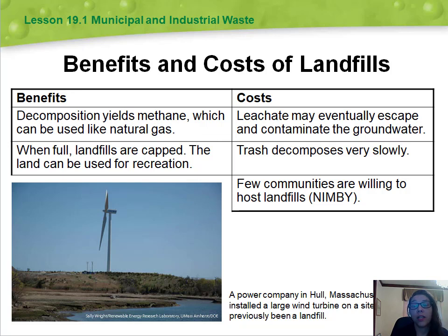So let's look at the drawbacks of landfills. Despite improvement in technology, many experts believe that leachate will eventually escape even from a well-lined and well-maintained landfill. Liners can be punctured and the leachate collection systems eventually cease to be maintained. Moreover, landfills are kept dry to reduce leachate, but the bacteria that break down material thrive in wet conditions. Dryness therefore slows waste decomposition.